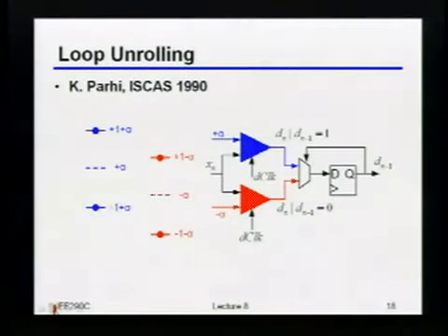The last thing we ended up on was that if you really want to push it, and if you don't want to move all the way into CML, or even beyond certain data rates in CML, you might have to do this. There's this basic idea of not really closing the loop, but instead doing what's called a loop unrolling technique. We talked about this a bit last time, but just to make sure it's really clear, let's say we really couldn't deal with that very first tap.